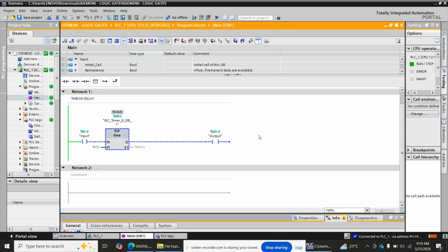So input turning back on resets the timer. If you flip the input switch again, maybe the sensor has seen a box, it waits 5 seconds before it turns off. Let's say you have a conveyor and a timer off delay. Let's say on the conveyor, here is the input, here you have an exit sensor, so that when the boxes have exited from the conveyor, then wait for 5 seconds before turning off what? The conveyor motor. Now if boxes keep coming from time to time, this sensor will keep sending a high signal, and if it sends a high signal before the 5 seconds is reached, your conveyor will keep running. Then when the boxes finish, and the last box passes and 5 seconds pass without any other input, without any signal from the sensors, then the conveyor shuts off. I think you're getting the picture.